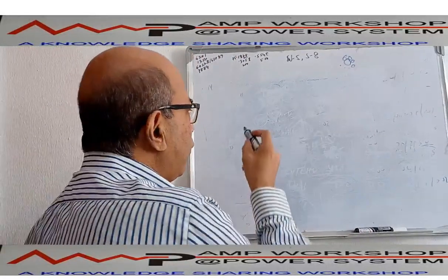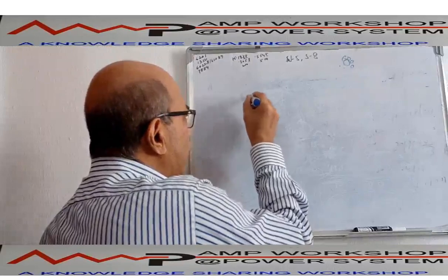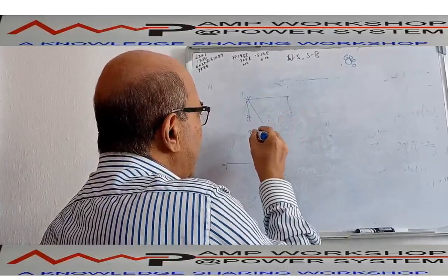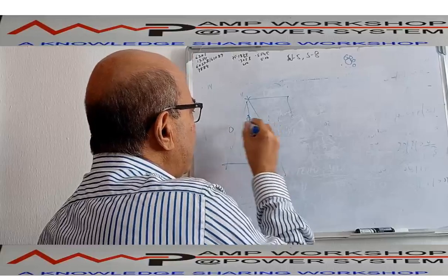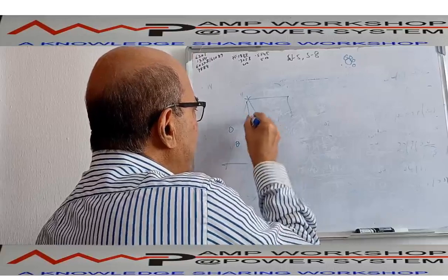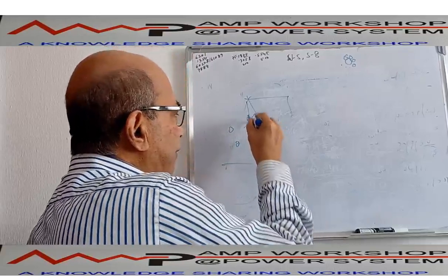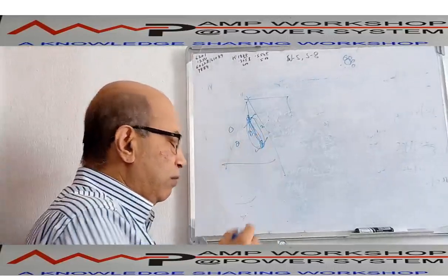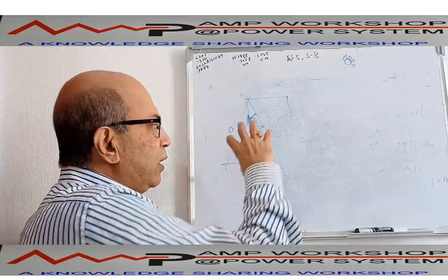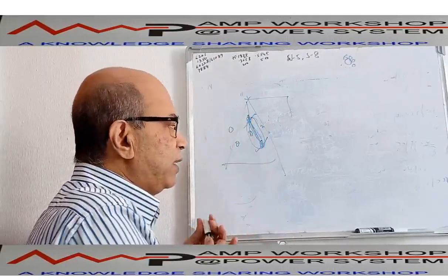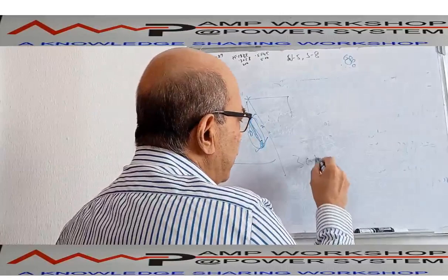In the case of conductors, when the conductor is going through the tower, suppose this is a tower and this is a hanger and the conductor is hanging over here, suppose there are three conductors this way, this is one conductor, this is one, this is one, there is a gap between these two. Now due to this gap, there is an electric field in between this. Now due to this electric field, this can break down. Normally this system is designed for 30 kV per centimeter.